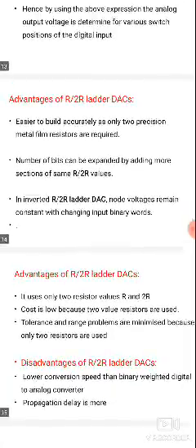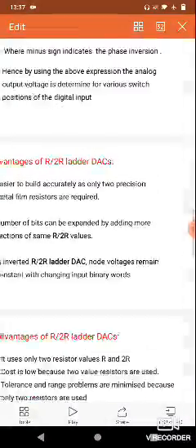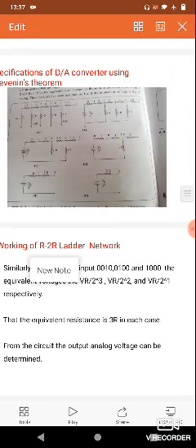So, Thevenin's theorem, how can we apply it? The application is: first open two terminals, removing the load circuit between which you want to find the Thevenin's equivalent. First of all, we remove the load in the circuit, and then we determine the Thevenin voltage, the voltage across the open terminals, and at the same time determine the resistance.